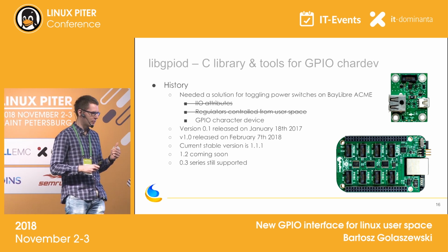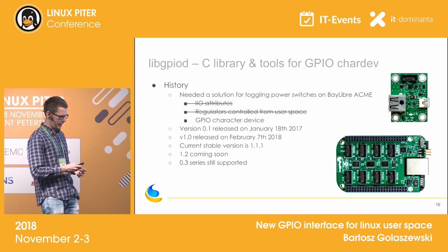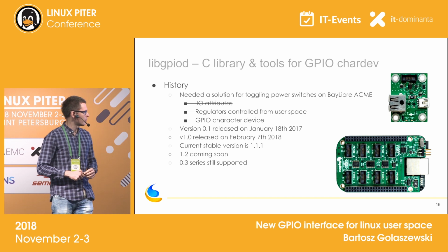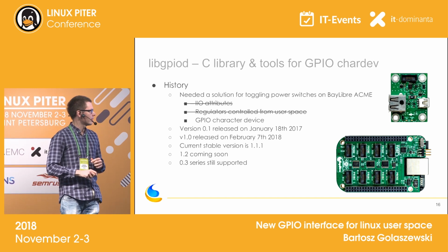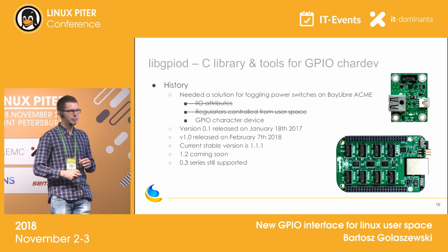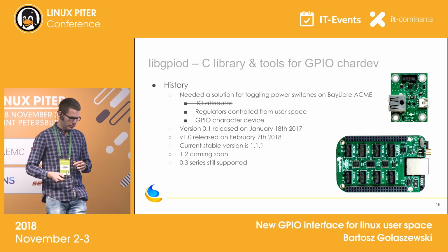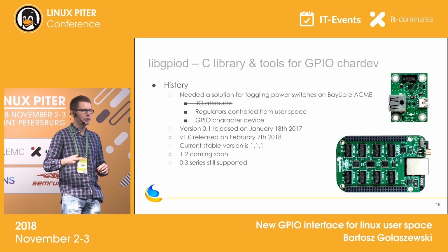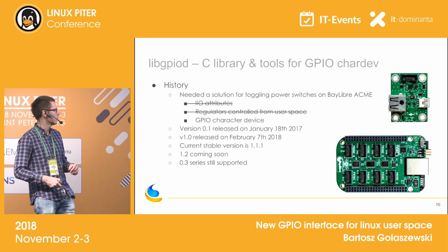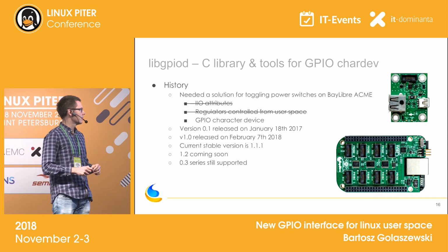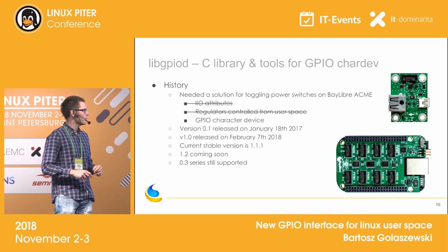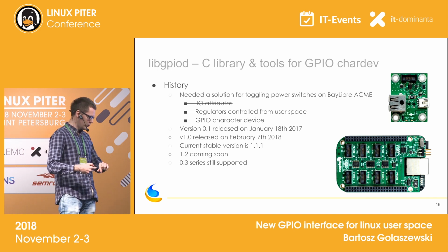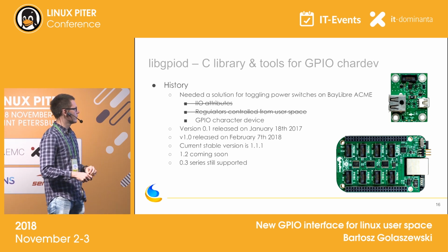So a bit of history behind this project. We at Libre have designed this power measurement cape. It's called ACME, and it comes together with power measurement probes. And on these probes, outside from the power monitor, we have a power switch, and we wanted to drive it. For instance, if you're measuring a board, you want to power cycle it to just measure its power consumption at boot time. These monitors were actually driven by industrial input-output drivers, but we also wanted to toggle the power switches.